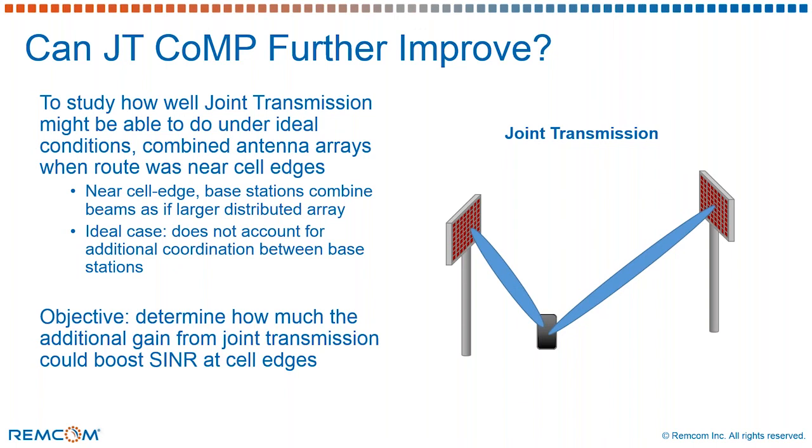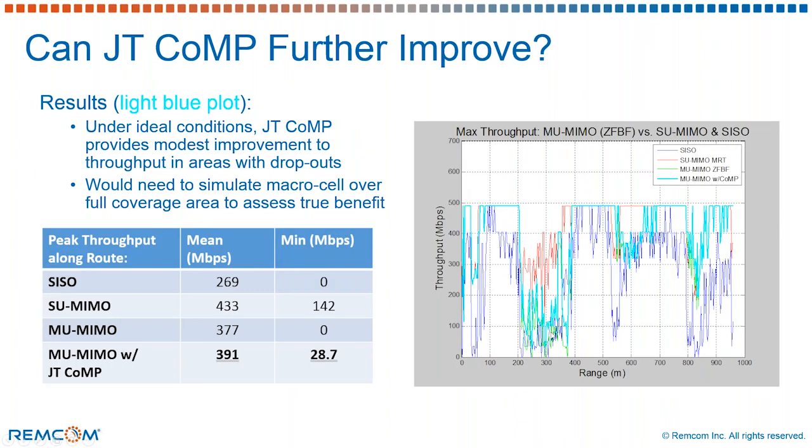The first is channel reciprocity. While physics states that channels are reciprocal, the uplink and downlink transmitter and receiver chains are not. And most of the adaptive beamforming techniques, such as the one that we present today, use pilots that are coming in the uplink to then determine how to form beams in the downlink. So this channel reciprocity becomes extremely important to deal with.